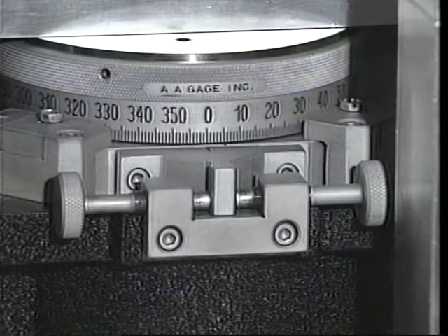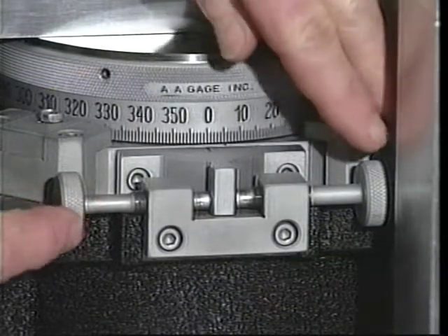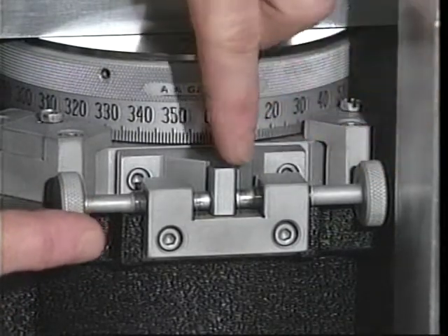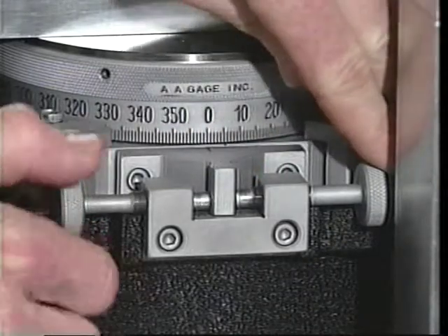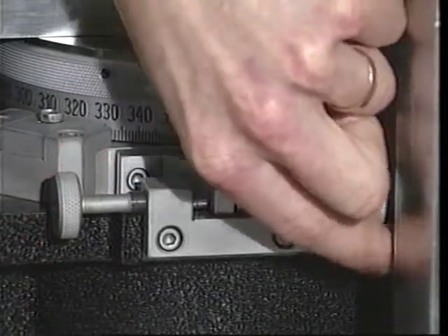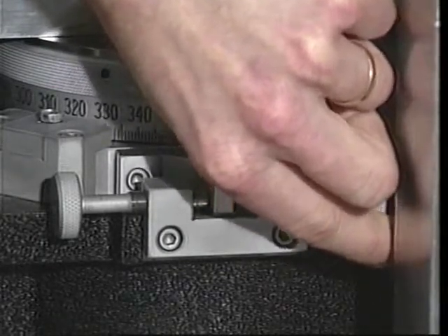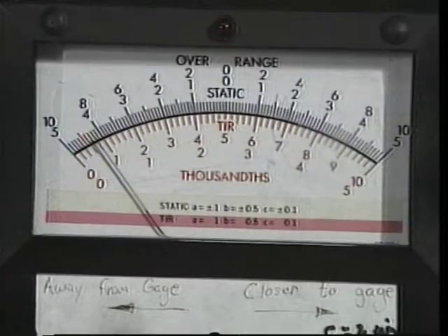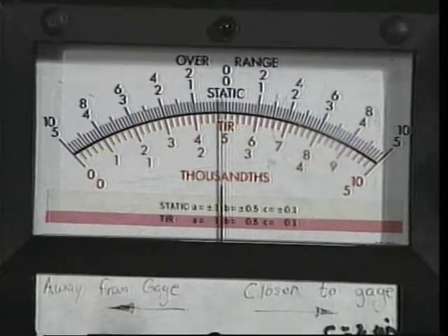The angular position of the straight edge is adjusted using the angular fine adjustment on the precision index. This fine adjustment consists of two opposing fine-pitch screws which deflect a paddle attached to the bottom half of the index. Depending on the sign of the change in the separation of the probe and the straight edge, one of the screws is withdrawn and the other screw is advanced, thereby causing a deflection of the paddle and a small angular change in the position of the index. The angular position of the index is fine adjusted until the original probe straight edge separation is obtained.